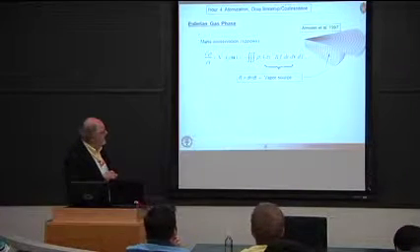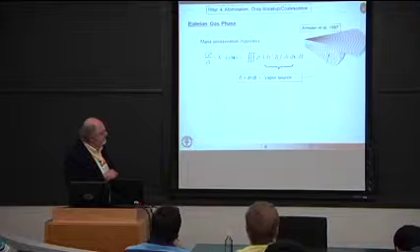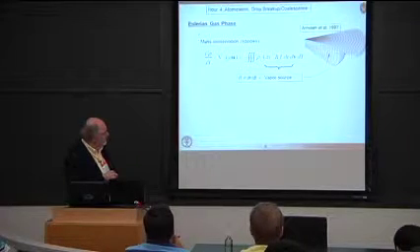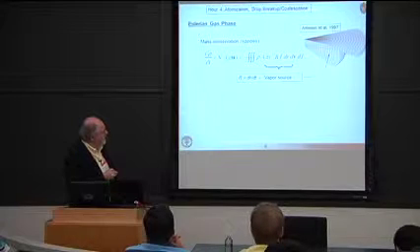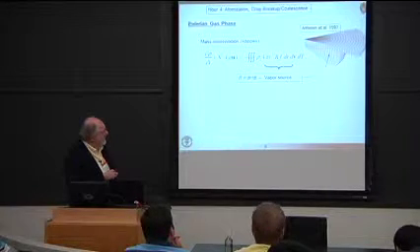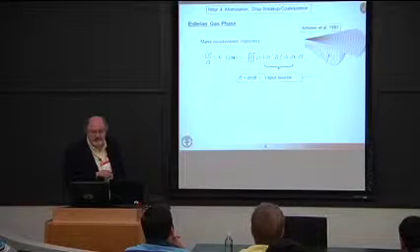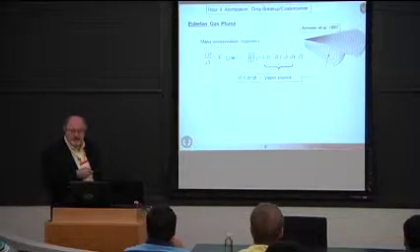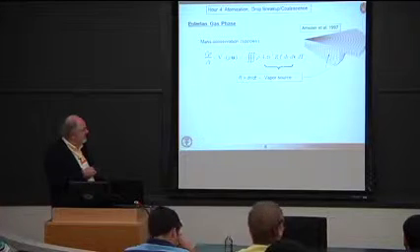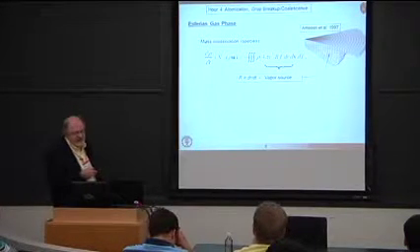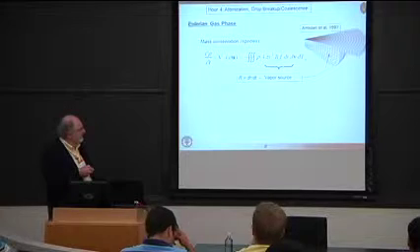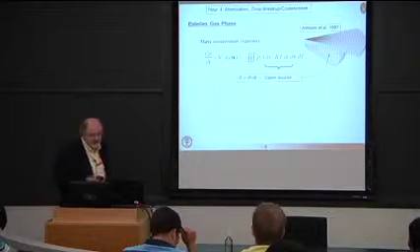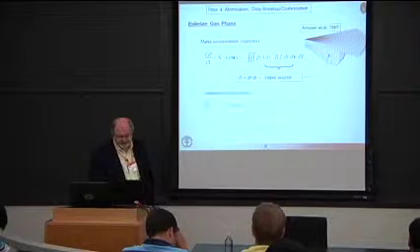And we can keep track of that by, if we knew the distribution function of the droplets, integrating over all the droplets in a computational cell and multiplying by the surface area and the vaporization rate of the droplets. So R here is a parameter we have yet to specify, and that's going to come from submodels. It essentially says the rate of change of droplet radius with time. We need to know that in order to calculate the source term associated with vaporizing droplets.